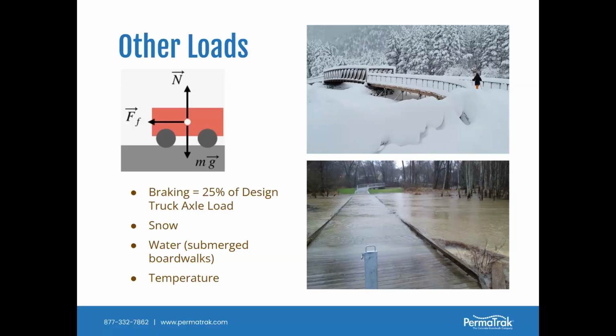Water, submerged boardwalks. Boardwalks are in wetlands, boardwalks are in floodplains, and you're going to have this hydraulic force, this hydraulic loading, not just submerged, but velocity of flow coming from one side, pushing on the boardwalk, and stream debris. So those are some things that need to be considered also. And lastly, not to be ignored, is temperature loadings, temperature effects. As the temperature goes from one gradient to another, that causes some movement in the components of the system, and the system needs to be designed to account for that. That's best handled by proper detailing in the boardwalk itself.